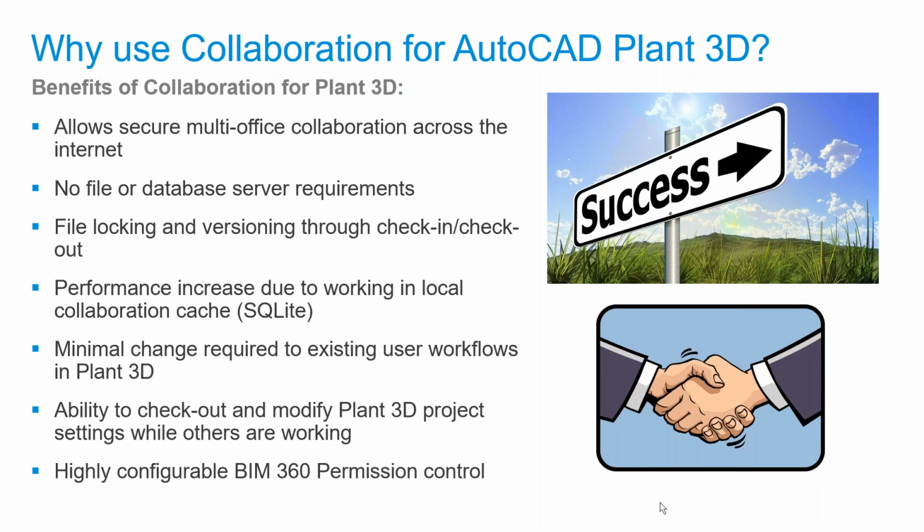The other nice thing is that when you go to something like this, you can check out and modify the project settings while other people are working. So you noticed before, like with a SQL Server project, you have to kick everyone out of the project if you want to just go in and add a P&ID symbol or make some changes, and then everyone can go back in. With the way this is set up, one project admin can check out those settings and work on them during the day, and then check those in and synchronize that out to everybody else. So that's one nice thing about this as well.